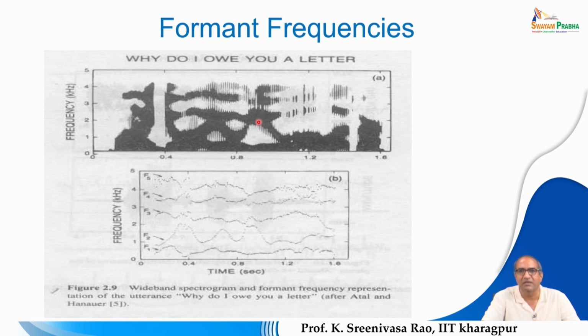The frequency ranges are where most of the signal energy will be captured, right? Here is the spectrogram. For visualization, for analysis, or for later computational purposes by a machine or some other means, it's difficult to handle the spectrogram directly. Therefore, here we will try to derive the formant plots. Formant tracks are nothing but the frequency ranges, showing how the energy distribution is taking place.